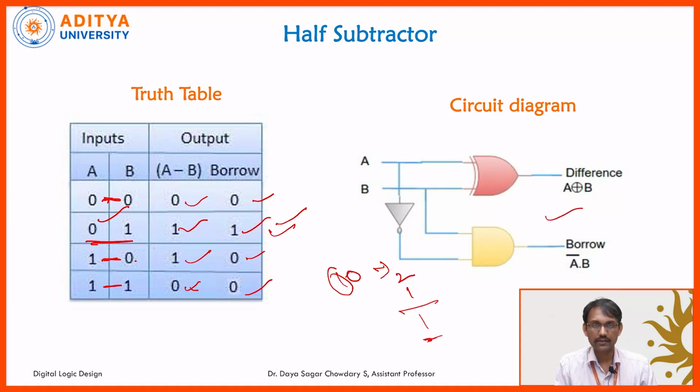And this is the circuit diagram. Anyway, we have to represent this circuit with the K maps. We have to use the K map, then only we will get the circuit for this particular truth table. So we will get the XOR gate. If we observe both adders and subtractors, the XOR is the possible circuit for both. Anyway, it is producing the correct value. And for the borrow, we are using an AND gate with the help of one NOT gate for one input terminal, that is A.